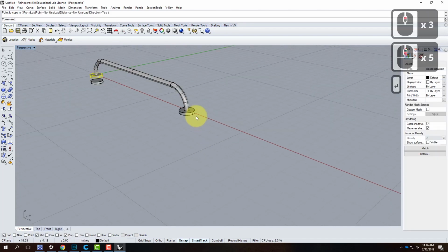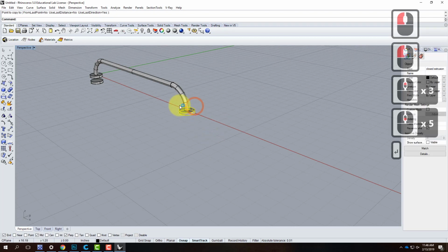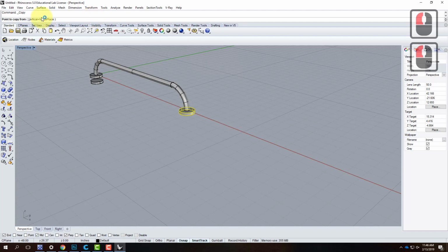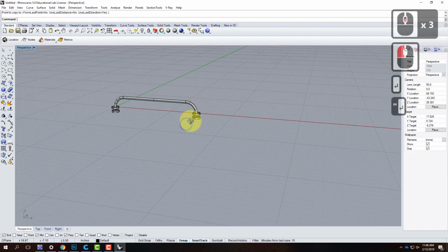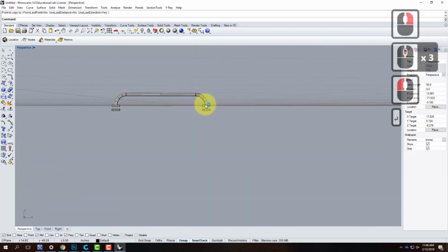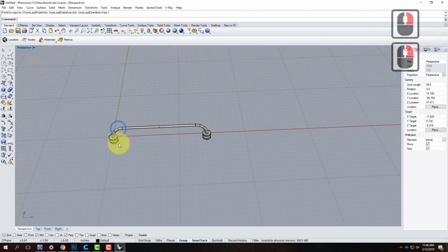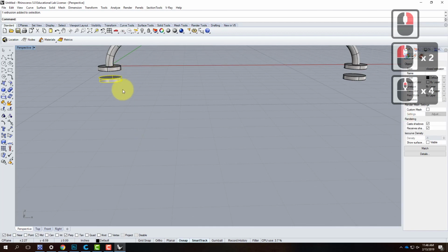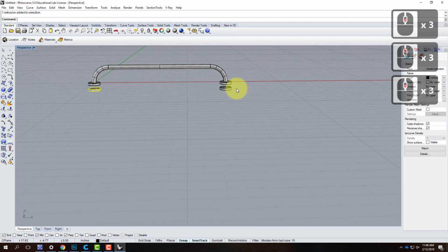I'm going to do the same thing over here for practice. There it is. We'll go to copy, so transform and then copy, or you could type in copy. Vertical is going to be set to yes. I'll click somewhere, doesn't matter where, and we'll do negative 0.75 inches, like that. I'll press enter to finish, and now I have this bar or rod or whatever you want to call it. I have two buttons on either end that are separated by a ½ inch of space. Long term, we're going to end up putting some glass in between those two pieces, there and there.